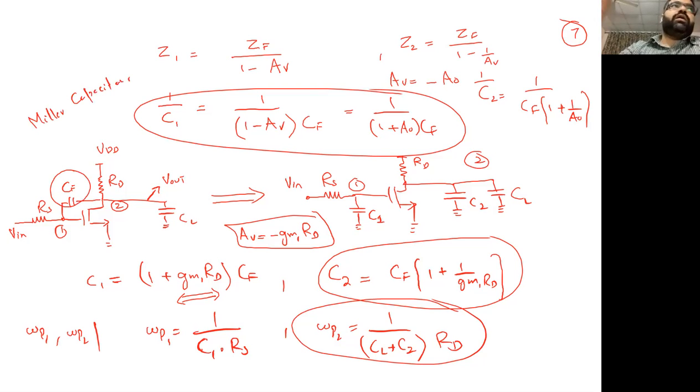And this whole theorem is known as Miller theorem. Okay, so moving forward, now we know this thing. It can be applied to inverting amplifiers. It can be applied all the time whenever the capacitance, or resistance, is in between two nodes. So we can write the gain should be inverting.